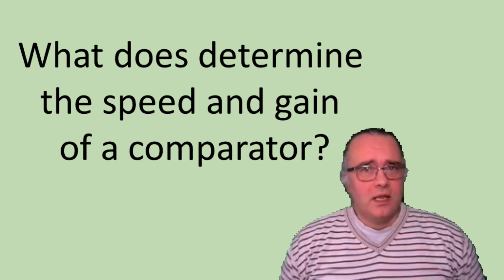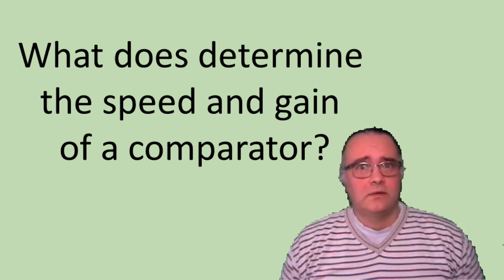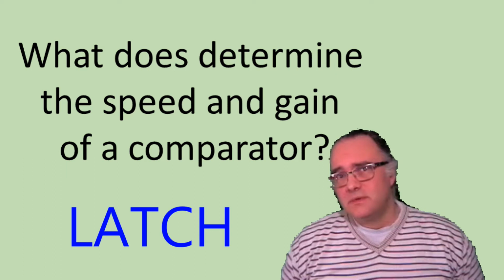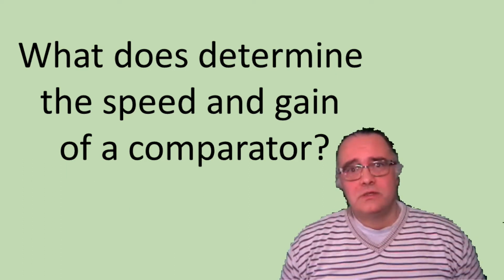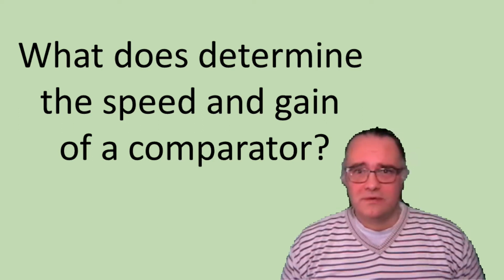I will analyze the relationship between speed and gain of the core of the comparator, the latch, and I will establish its dependencies on the design parameters of the latch, the equivalent capacitance, and the equivalent GM.